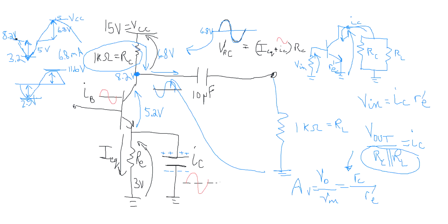They have to be equal. If I try to push more current through, that current would have to come up from the bottom here through my transistor into the load. And the one thing the transistor won't do is give you negative current. It won't transmit current in the opposite direction. We've said that before. So that's an impossible situation.